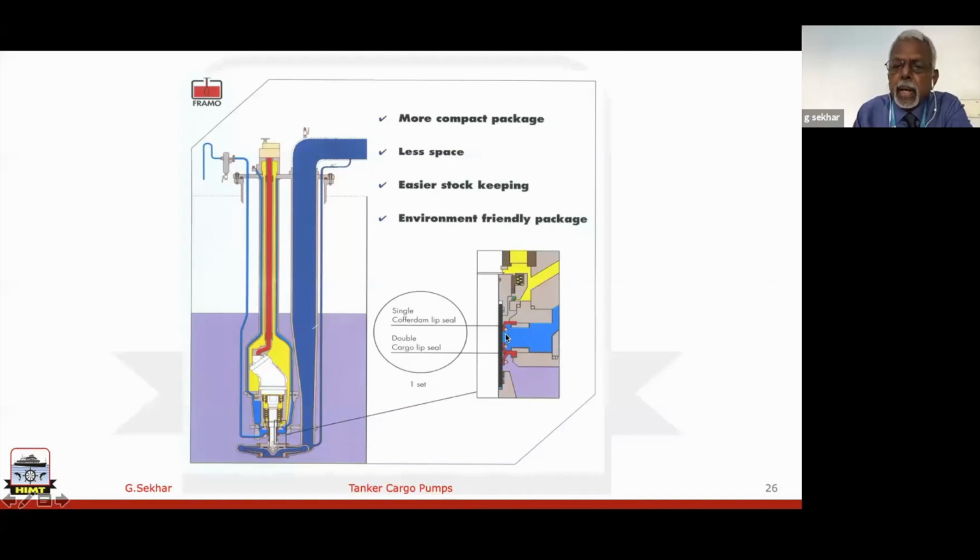Okay. Now here, in this line, the red line is your pressure oil, yellow is return oil, and here the blue line, what you see, we call it the cofferdam. This is supposed to be an empty space here. And in case there are seals here, there are bearings, everything is there. Suppose there is any hydraulic oil leak-off, that will leak into this cofferdam.